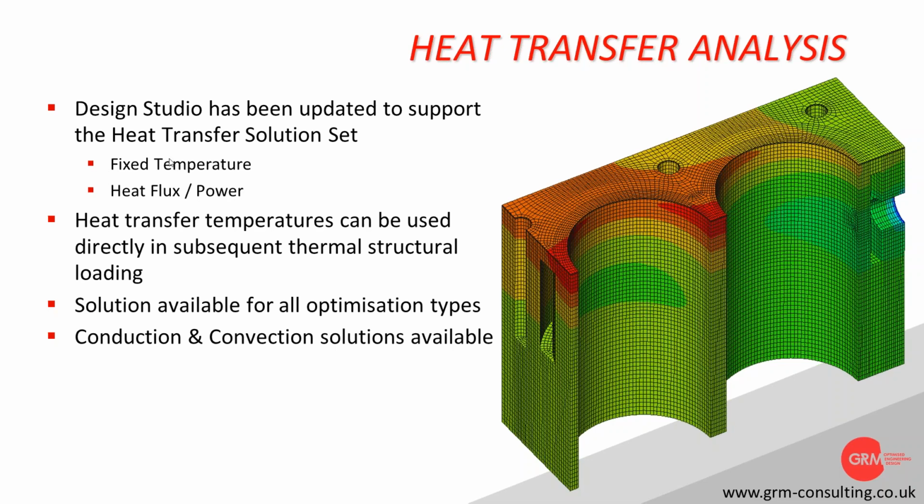The key thing is we've got fixed temperatures, heat flux, and heat power we can apply to the model, and the solution set is conduction and convection solutions. These couple directly to the structural solver, so we can have a heat transfer calculation followed by a subsequent thermomechanical directly in the solve.